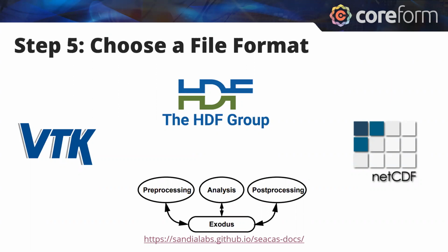Largely there'll be some combination or selection of these, but there are also some text-based input files. I know that a lot of open source tools have built upon the Abaqus input format or off of the ANSYS format, so you can certainly use those as well. I want to point out what's nice with these tools: VTK is natively supported by ParaView.